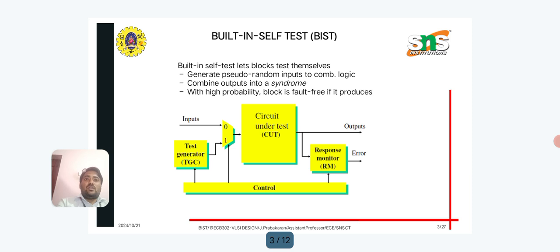And the BIST controller. The built-in self-test controller orchestrates the entire testing process. It controls the operation of the TPG, coordinates the application of test patterns to the circuit under test, and manages the response analyzer. The controller also determines when the system enters or exits test mode, and handles switching between normal operation and BIST operation. The controller may be activated externally through input or internally through built-in logic such as a timer or a control register.